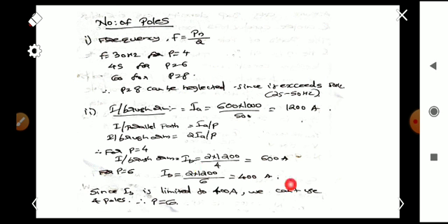400 ampere. So the second condition is within the allowable limit, that is, current per brush arm should not be greater than 400 ampere. So we can adopt the value of P is equal to 6. That is, IB is limited to 400 ampere, so we can't choose P is equal to 4. So here we are choosing P is equal to 6.